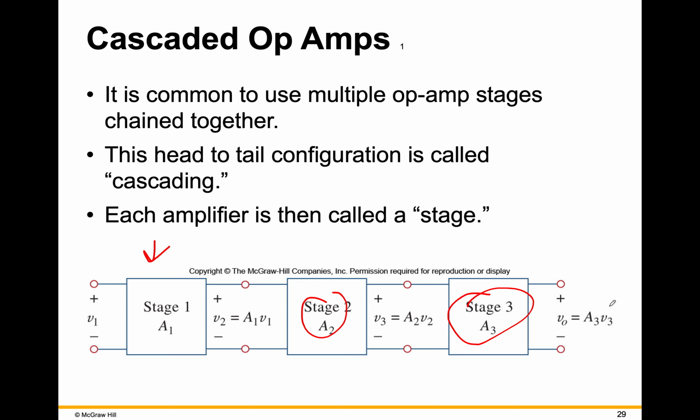Yes, theoretically you can do it an infinite number of times, but in practice it becomes pretty difficult because each op amp, to make it work in an optimum way, has to be tuned a little bit in the lab. So you do leave yourself open to a little bit of vulnerability if you try to stage too many op amps together in this way. Basically your gain gets too high, and that can create some problems with things like frequency response and some other things.